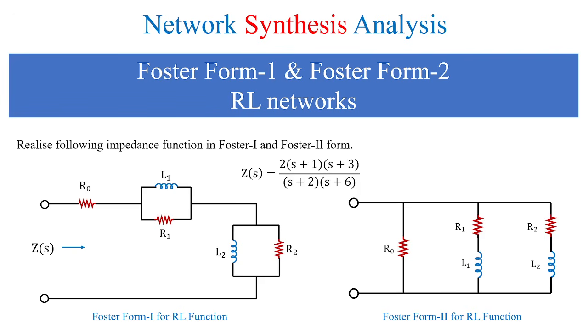In today's class, we are going to learn about Foster Form 1 and Foster Form 2 for RL networks. Here you can see an example of Foster Form 1 for an RL circuit, in one form that is impedance form and another one is in admittance form. So how we are going to frame these two forms, we are going to see in this session.